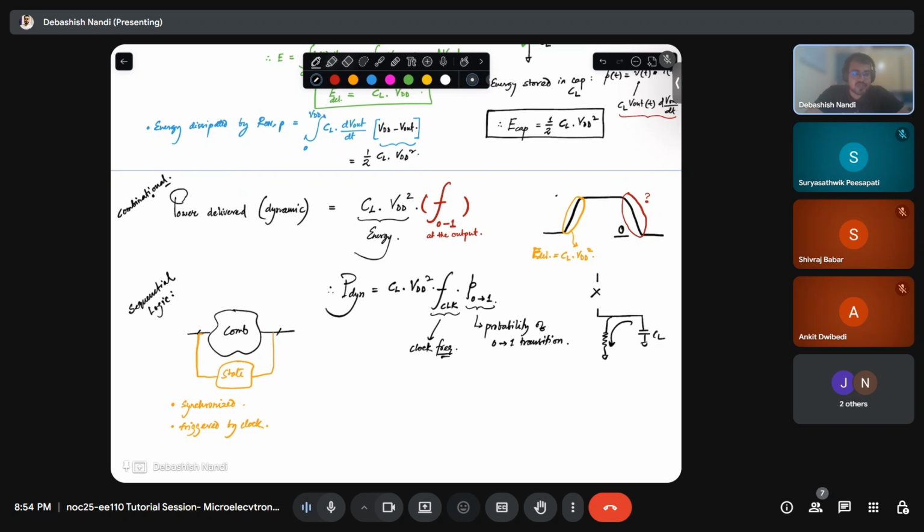So by the way, what is the clock frequency in your computer? Can anyone tell me what is the range? Sir, 1.5 gigahertz to 4 gigahertz. That is very low. Yeah. It is around the range of 1.8 to 4.2, 4.3, right? Similarly, sir, in high performance systems, for high performance servers and all, you can have up to 5.2 gigahertz, right? Beyond that, if you increase your clock frequency, you will generate so much power and thus so much heat.